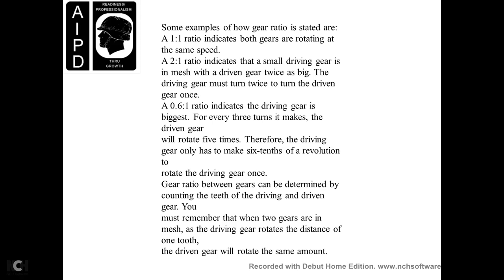The gear ratio between gears is determined by counting the teeth of the driving and the driven gear. You must remember that when two gears are in mesh, the distance of one tooth on the driving gear will rotate the driven gear the same amount.